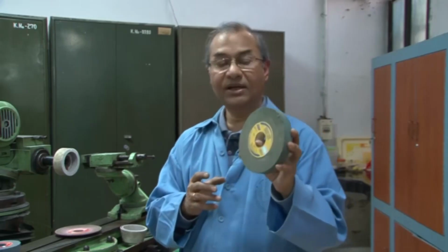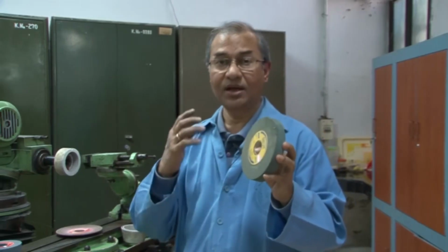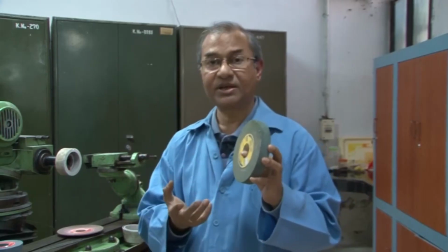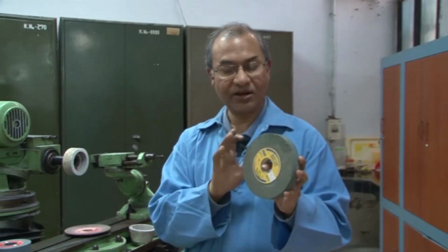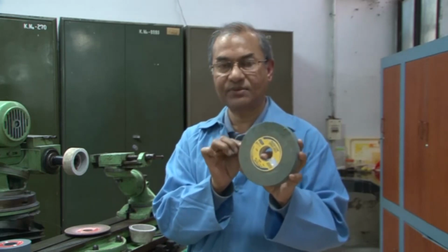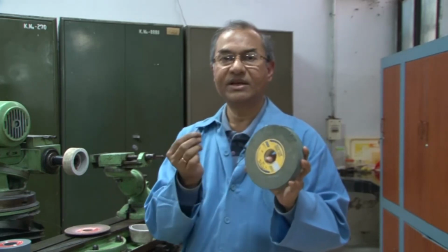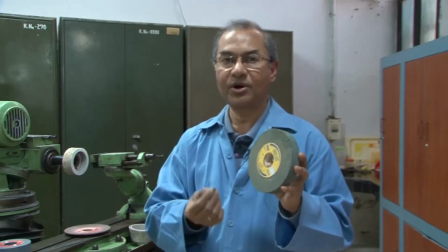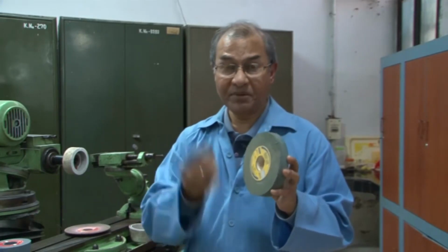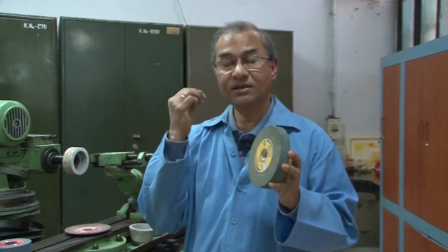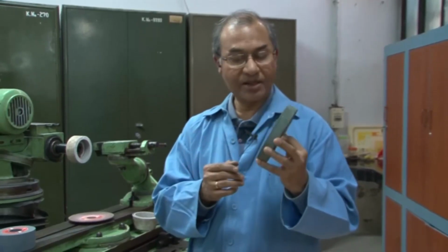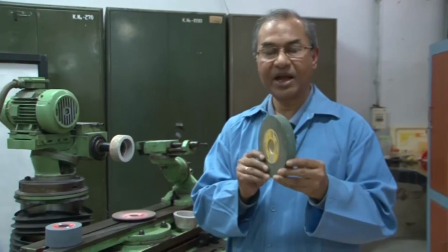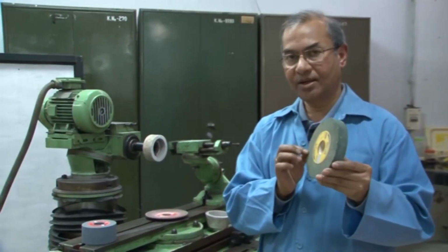For example, for grinding steel, or hard, high strength material, aluminum oxide (Al2O3) abrasive grains should be used. When silicon carbide is used as the grains of the grinding wheel, it is for materials like aluminum, copper, brittle materials like cast iron, or highly hard materials overall. Those workpiece materials are ground with a grinding wheel with silicon carbide grains.